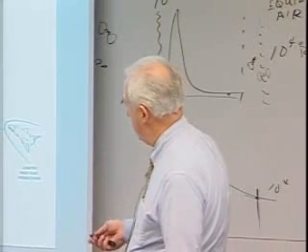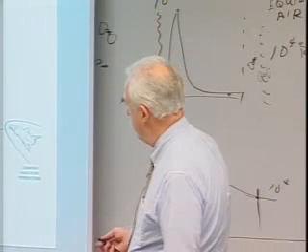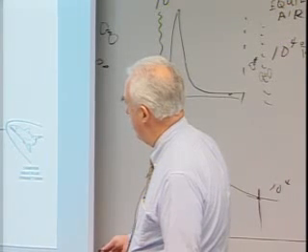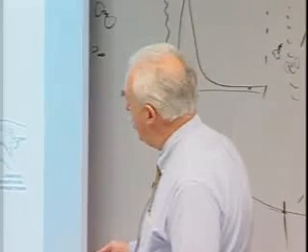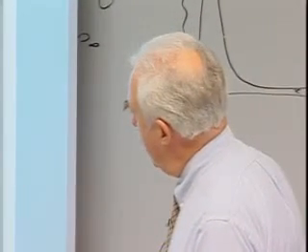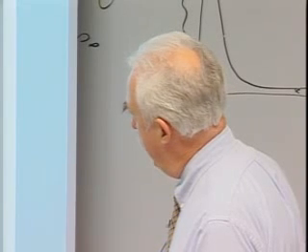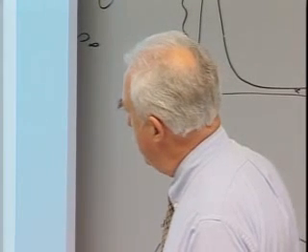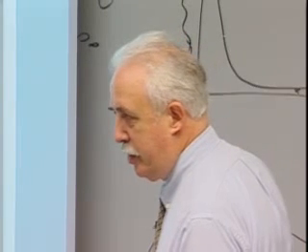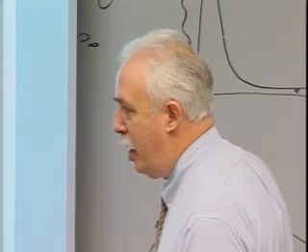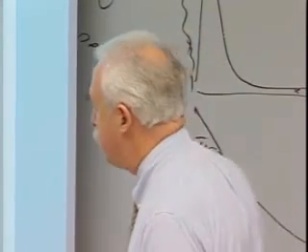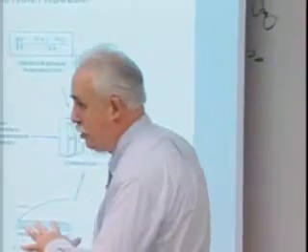This is just the concept, which again, as Aaron mentioned, is in the report. We had to go to arc jets and spectroscopic diagnostics and flow models of what's going on in the arc jet to understand the surface catalysis of tiles and carbon. We had to model the flow and model the chemistry, come up with an efficiency. Then we go to flight with similar analysis and predict, and I'll show some predictions of this. This is a significant phenomenon at the high altitudes, low density for the shuttle. Okay. Any questions on surface catalysis?